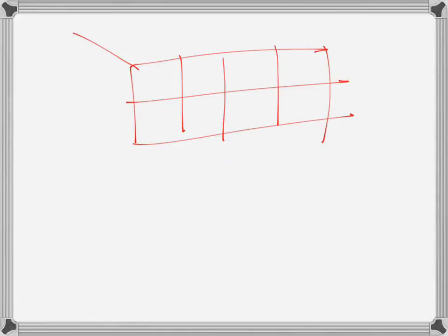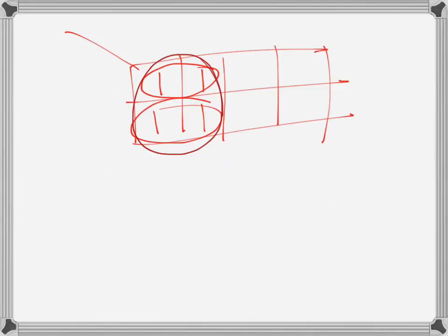So let's say I will draw again. So this one, let's say we have a 1 here, and like that. So instead of making these two groups, that won't give us a minimized expression, we will make the bigger one. So that's just one group. So one group as big as possible, and we have to take all the ones in the K-map at least once, but we can have overlapping of groups.